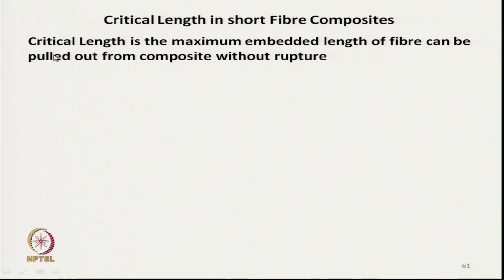So, the critical length is the maximum embedded length of fiber that can be pulled out from the composite without rupture. As I have mentioned, if it is more than the critical length, that fiber will not be pulled out, it will rupture.